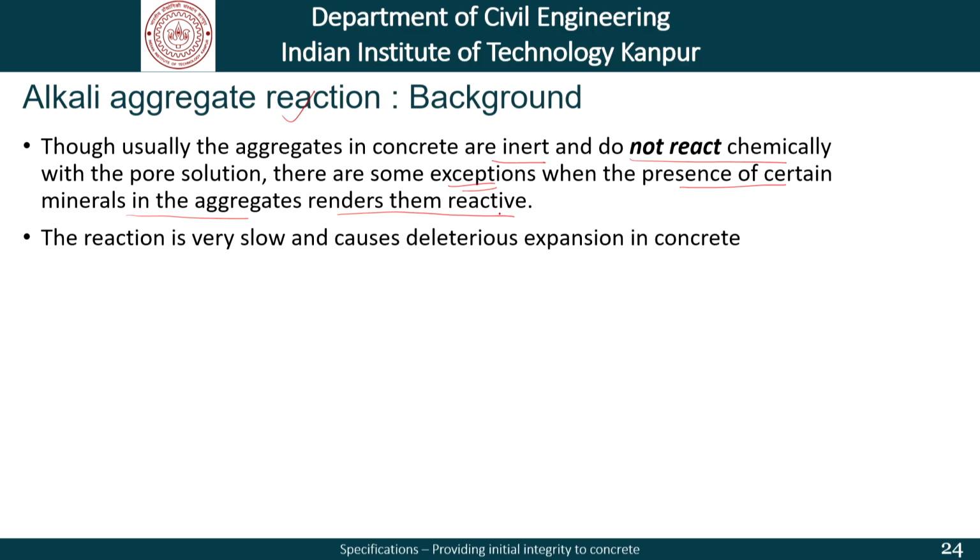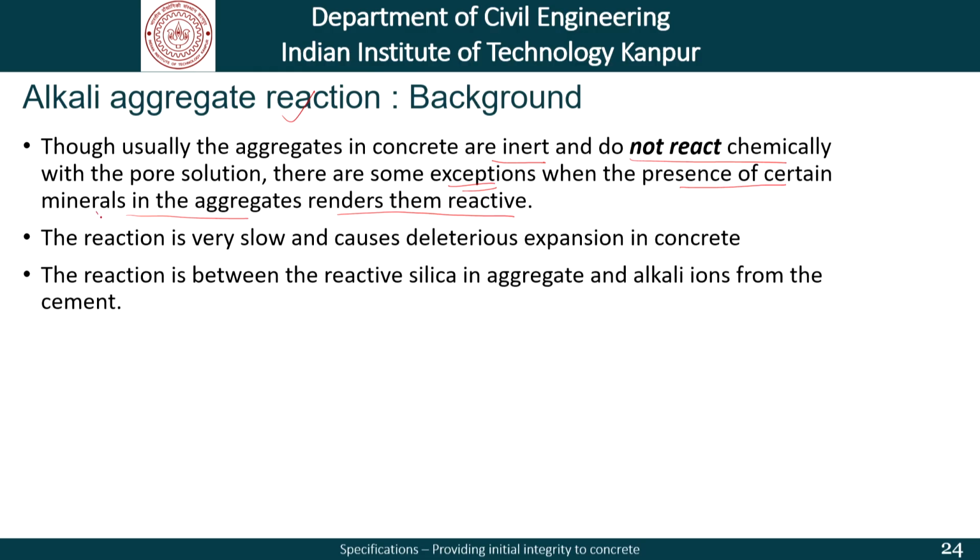This reaction is very slow and causes deleterious expansion in concrete. It is between these minerals, called reactive silica, and the alkali ions from the cement. As far as alkali aggregate reactions in concrete are concerned, there are two prime players or factors.